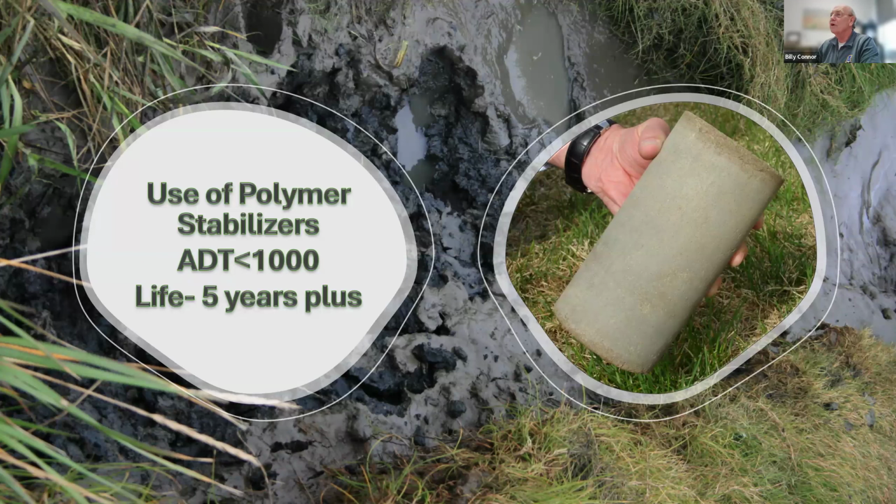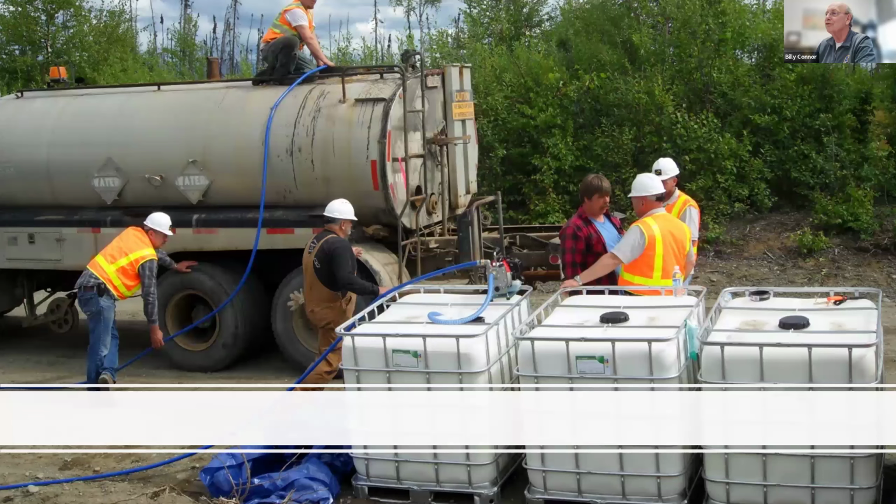The nice thing about these polymer stabilizers, they do come in a powdered form, so all you have to do is keep it dry. You can let it freeze. But if you decide you want it in the liquid or emulsified form, please do not allow it to freeze. You want to hold it in warm storage somewhere so that it cannot freeze. Otherwise, you'll lose it. And we tried to put it back into solution, and we were not able to do so.